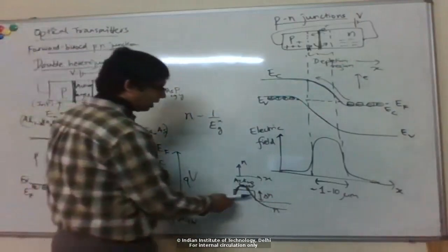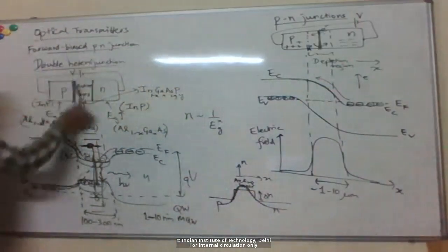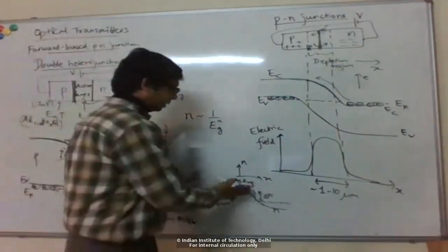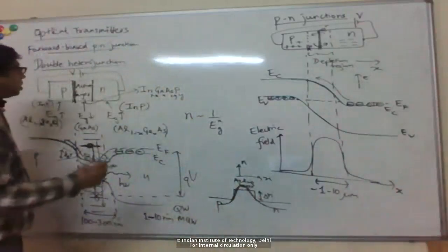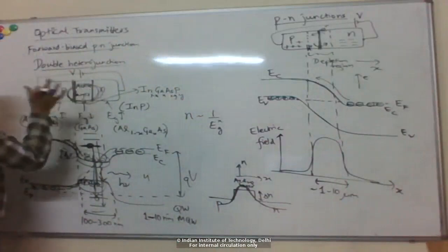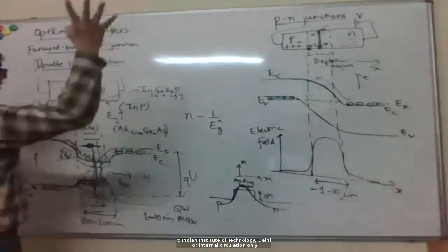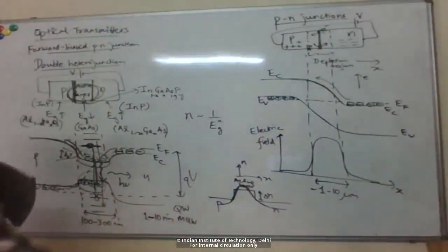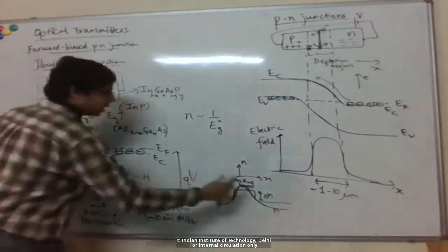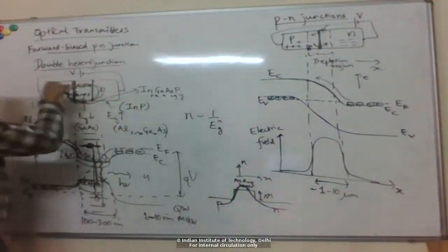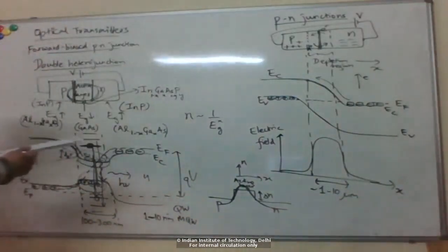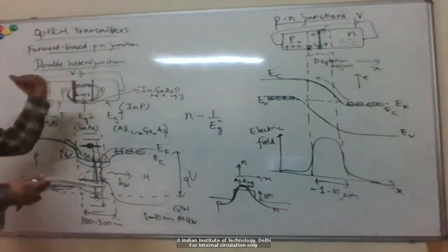So this thing acts like a waveguide. Of course, this confinement is only in one direction, not in this direction. But still, you do get some waveguiding or confinement, so that the light coming out is a nice optical mode coming out of the device. It's not spreading light everywhere. Imagine a thickness to this device into the board, then the light will travel in this middle active region like a mode. It's like a slab waveguide. So you get this additional waveguiding effect, which also enhances your directional emission.